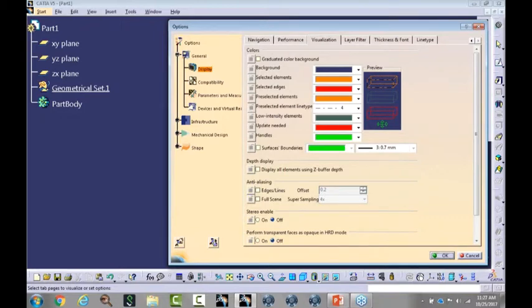And it would make it easier if you had the ability to actually take your settings with you. Well, you actually do. This second tool down here says dump parameters values. What it allows you to do is create a directory or a file that contains all of this. Actually, it's a directory that contains all of these. You can put that on a thumb drive, hand it to the CATIA administrator at the other end and say, wherever I'm going to be logged in, please activate these values.